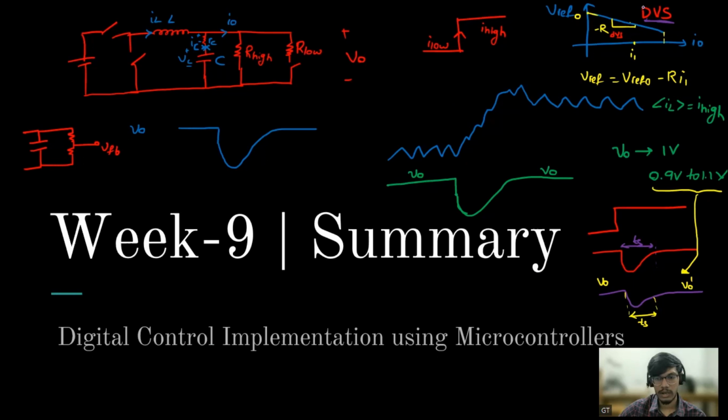So this concept is to scale the reference directly so that the transient will be faster. One more question is the undershoot of the output voltage. Sir, this capacitor discharge will happen up to the peak minimum value, right? Once the output voltage starts to rise after the minimum value, it means the inductor has started to charge. The drop will be instantaneous.